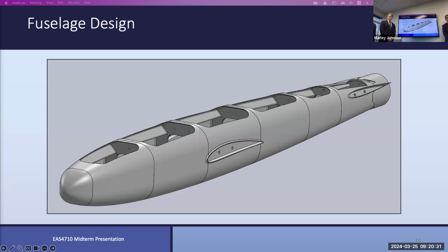My feeling is that it's probably not necessary, because there's so many openings. We only need one space where we can put batteries and replace batteries. What about servos and things like that? Don't those break pretty frequently? For servos, you don't need to have so many openings on the fuselage. The main purpose of the fuselage is to carry batteries and all the electronics, and you only need one opening. We have built many aircraft with previous methods, and only one opening on top is good enough. I mean, I don't know, and you mentioned that it's also for the purpose of some landing gear.